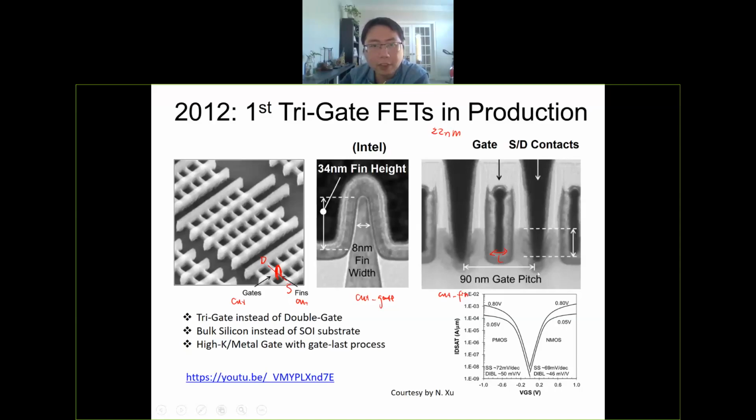And I just want to mention one difference between the FinFET and the conventional planar MOSFET, which is the W. In the FinFET, now the current is flowing along this sidewall. So effectively the W is this, because the current will flow along this interface between the fin and the oxide, the gate surrounding it.